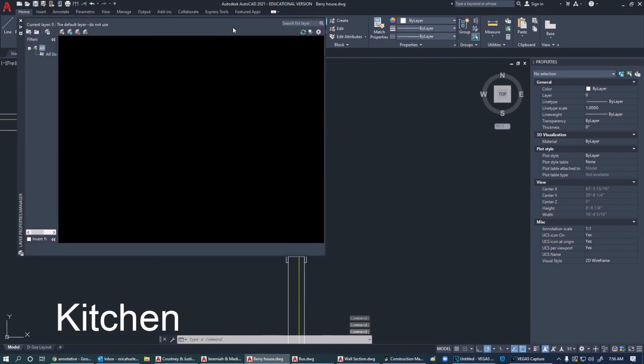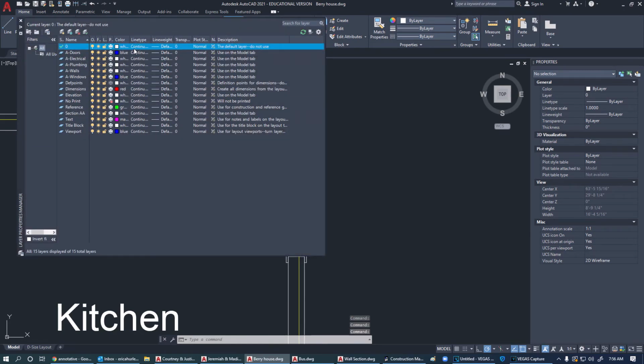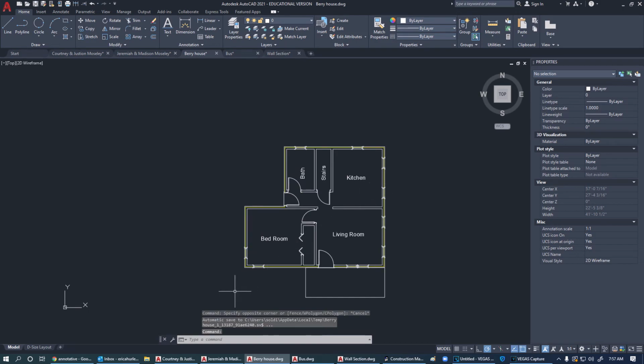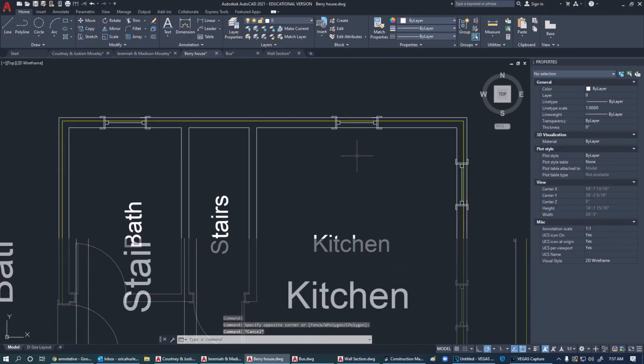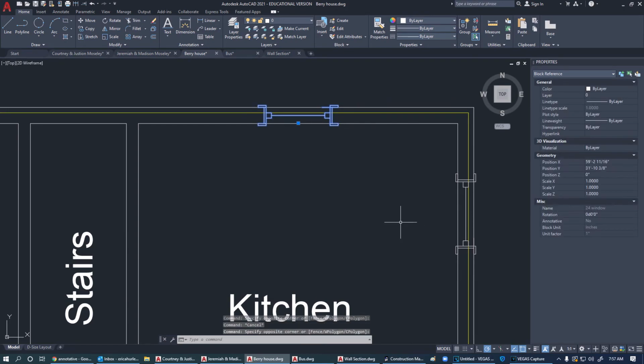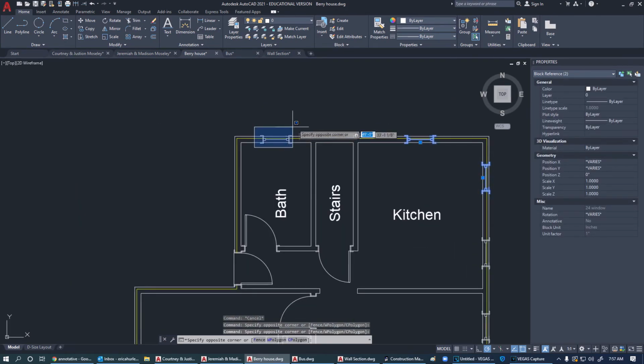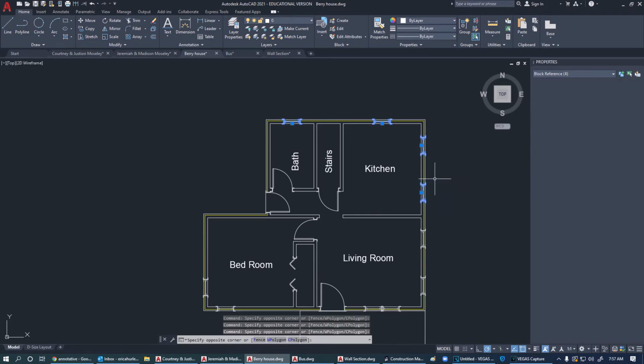So click on layer properties, and these are the layer properties that are currently available to you, and they have different names and so forth through here. So you'll see that currently everything that we've drawn is pretty much going to be on 0. Let's check that. If we highlight everything that we've got here, you notice that bam, it's 0. So let's go ahead and put our windows and doors into the category that they need to be in.